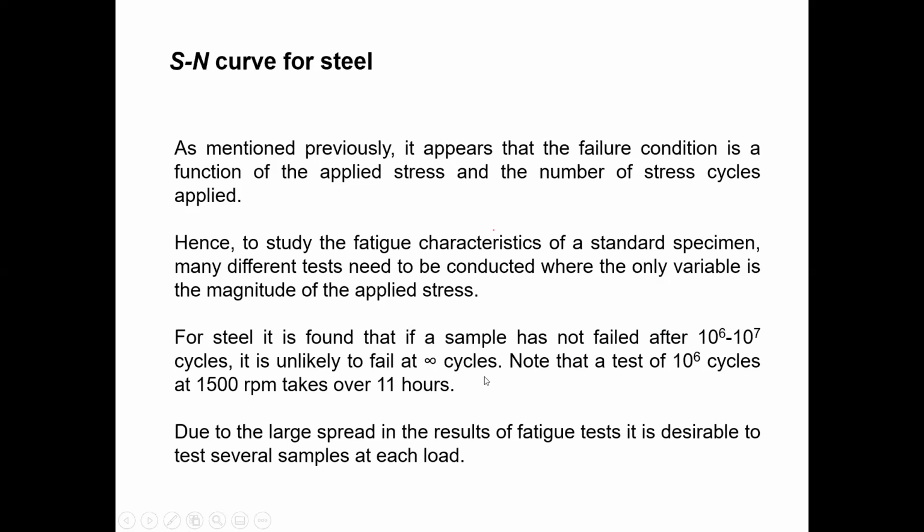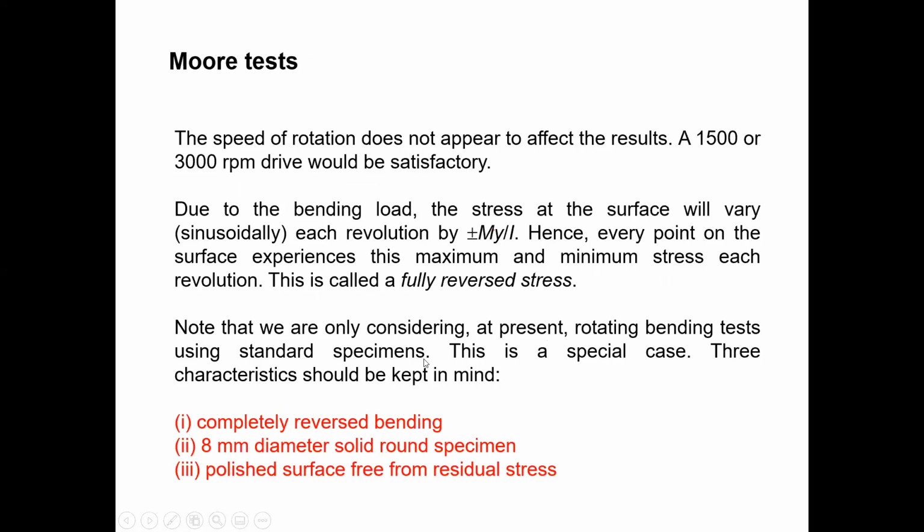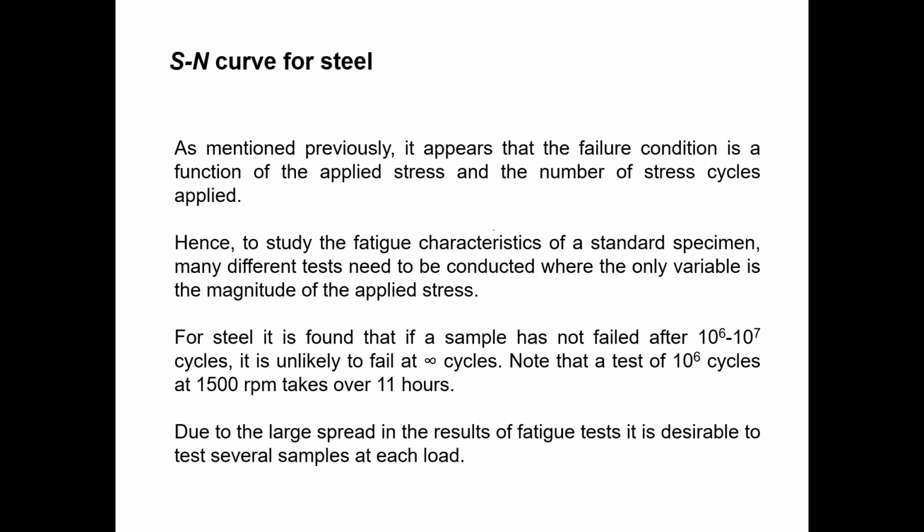So with this technique, we will draw the S-N curve. S-N curve means fatigue strength versus number of cycles. The test experiment parameters are given here, so you can read this one. I'm not going to go through too much about the RPM value. You can use a motor RPM value of 1500 RPM or 3000 RPM. Here they use 1500.